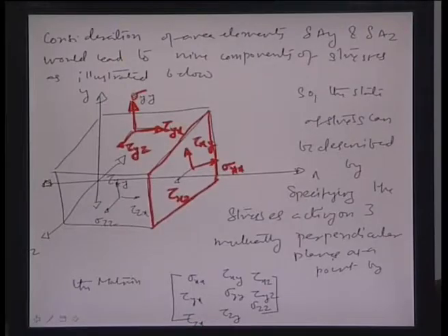So, that is what tau yx is, and similarly you have a similar combination on the third face here, pointing in the positive z direction. The area vector points towards the positive z direction, where you have sigma zz and 2 other shear stress components, tau zx and tau zy. This is very clearly illustrated here, showing how you can notationally express these different stresses in such a fluid element.